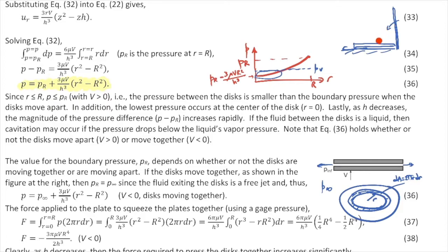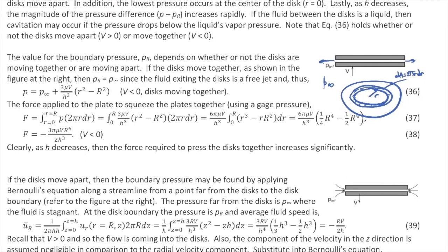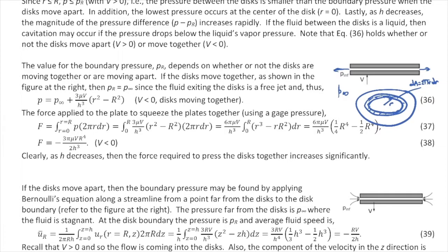As the glass pane falls and gets close to the surface, you're having to squeeze out this viscous fluid, and it ends up increasing the pressure in this gap region, and so it applies a force to the glass to decelerate it. And as that gap gets smaller and smaller, the force gets bigger and bigger, and it just helps decelerate the glass. So it's not a sudden shock to the glass when it falls against the surface. It's constantly being decelerated, so it won't suddenly impact the surface, and that's how they keep the glass from shattering. And you can see a similar analysis here.